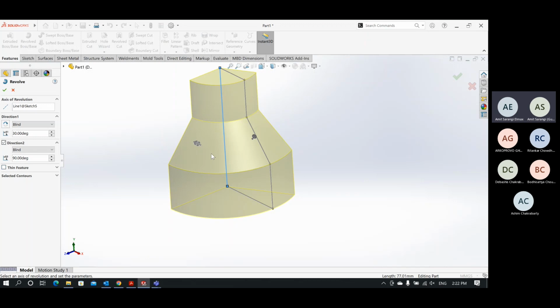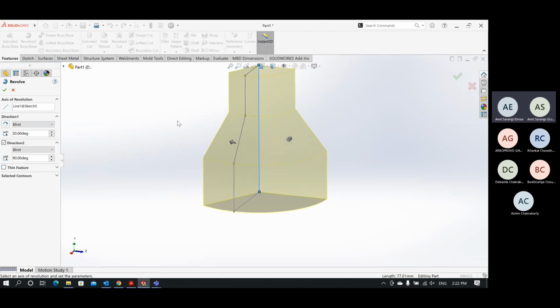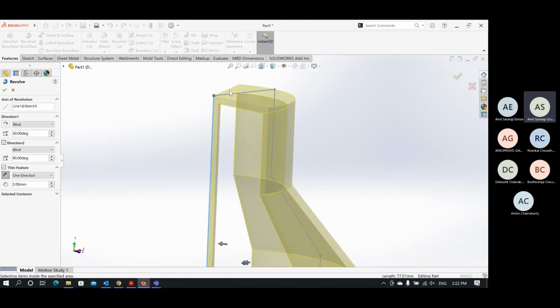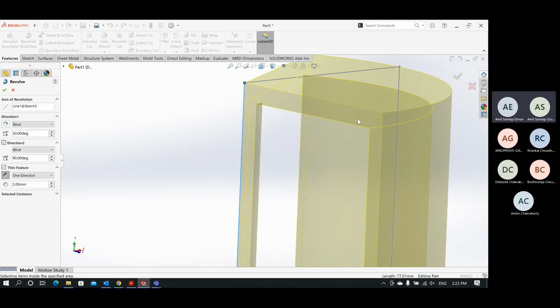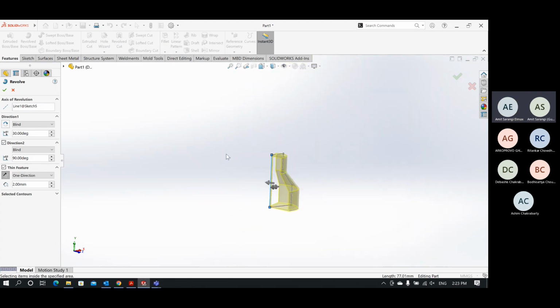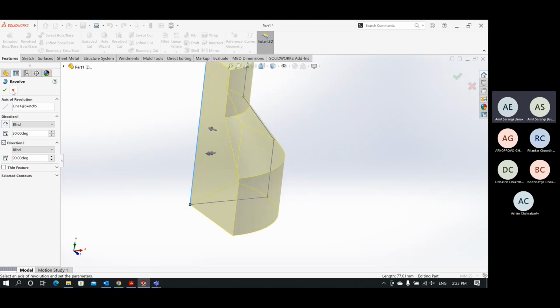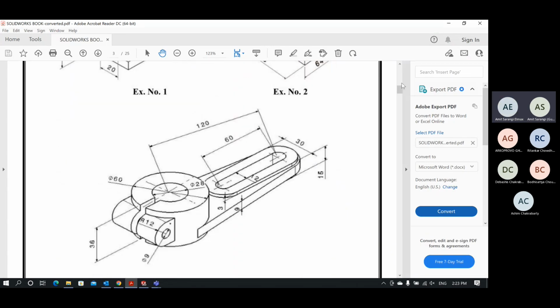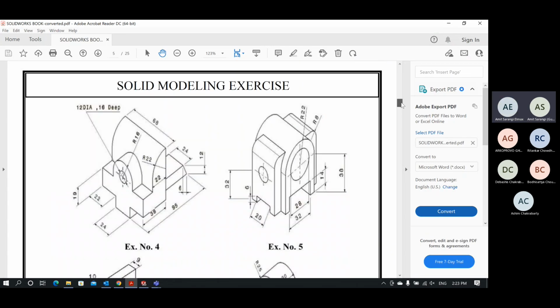And if you want to create a hollow kind of profile like we created in the extruded boss, simply click on thin feature and here you can define a dimension. Suppose 2. See, it is maintaining a thickness of 2 on each side. Getting me? But we want a solid profile, so we need not create it like this. So clear? This is how it works. If you have a symmetric kind of model, let me show you some example where you can use that one.